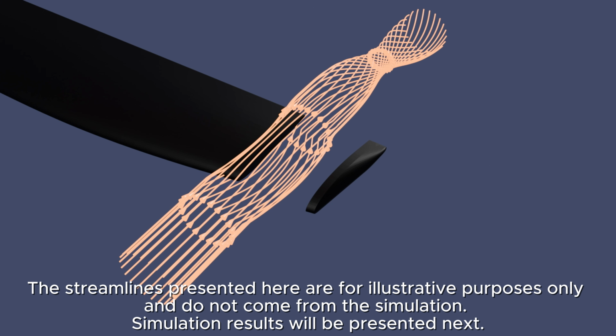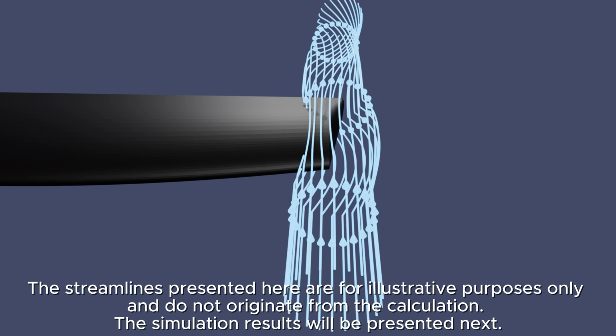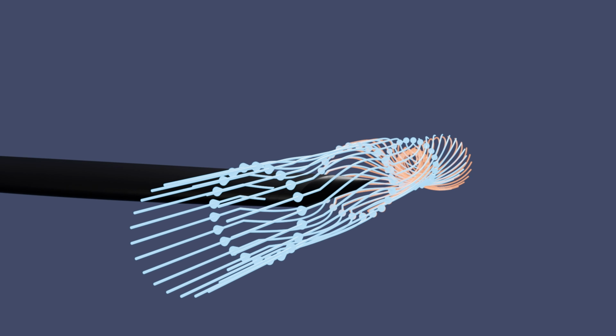First is the rounded tip. In terms of design, to minimize flow separation and reduce pressure drag, while considering the geometric continuity of the thin trailing edge, I set the start of the arc behind the chord line. This approach ensures that airflow passing over the wingtip transitions smoothly from the wing surface to the tip, avoiding abrupt separation at sharp edges, thus improving aerodynamic smoothness during low-speed flight while maintaining structural rigidity.